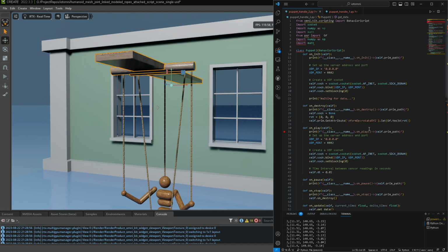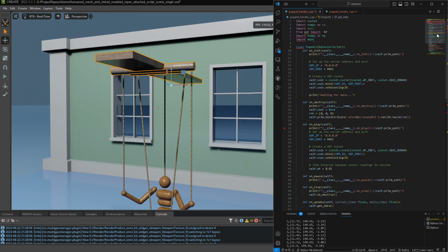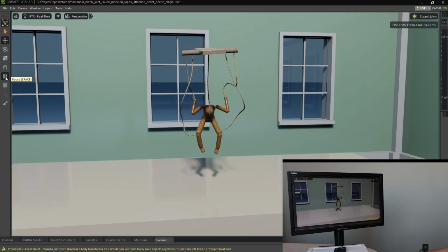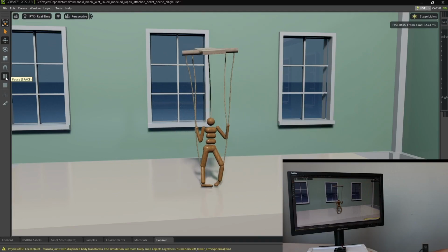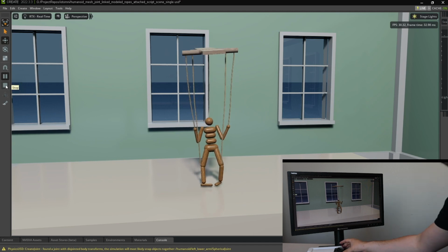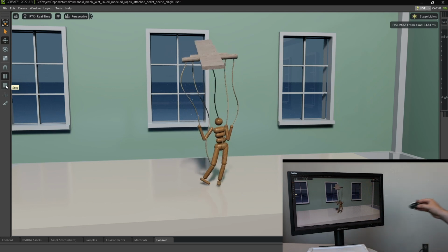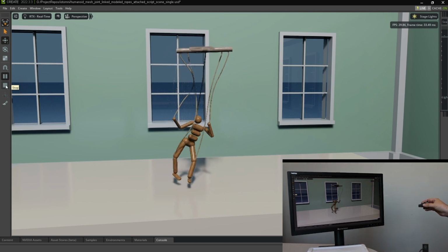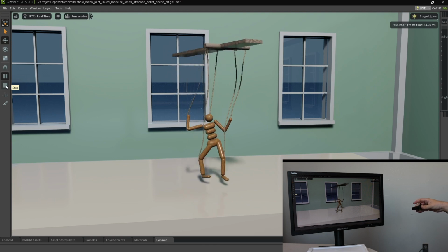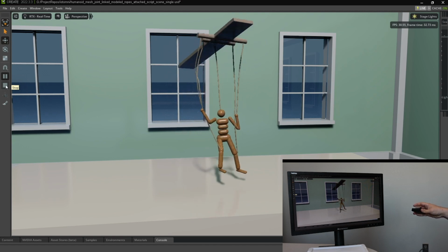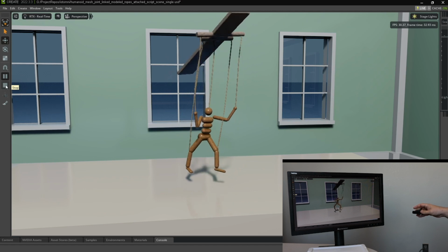All right, so the whole script is maybe 100 lines of code, less, 75 lines of code. A lot of it is boilerplate code. And at the end, we press play, the physics turn on, and the puppet connects. And on the bottom right, you can see I pick up this little AA battery pack that I have connected to the Arduino, and I can move it around. And it's pretty responsive, basically real time. It's running at 30 frames a second. And each frame is taking around 30 milliseconds to calculate.